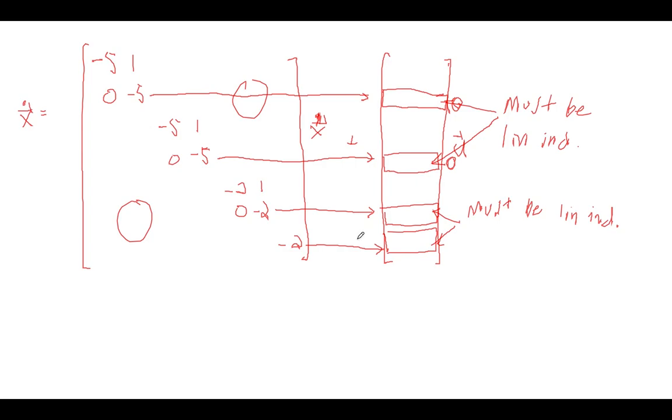Now, so far we've only been talking about controllability, but the same basic idea about what we can and can't know from our system applies to observability in the Jordan form too. So if we were to think of, for example, a set of outputs, and our C matrix, similarly to our B matrix, let's just write it like some generic C matrix, times X. And then there's going to be this DU matrix that's just not important at all.